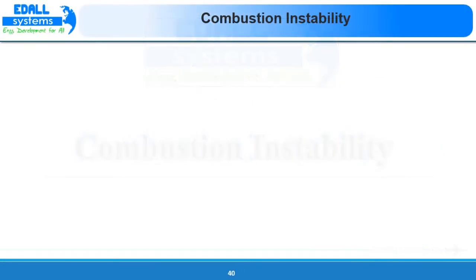Next we will discuss combustion instability. There are fundamental differences with liquid propellant combustion behavior. In liquid propellant there is a fixed chamber geometry with a rigid wall, and liquids, feed systems and injectors that are not part of the oscillating gas in the combustion chamber and can interact strongly with the pressure oscillations. In solid propellant motors, the geometry of the oscillating cavity increases in size as burning proceeds and there are stronger damping factors such as solid particles and energy absorbing viscoelastic materials.